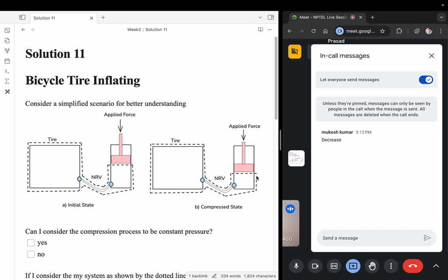in the question directly, but then you have to come to these conclusions. Either the question will tell you that it is insulated, which is a very straightforward one. If it is insulated, then it means there is no heat interaction with the surroundings. And then come scenarios like this, where the process happens so fast that even though your Q in terms of watts might be too high, the amount of time that the process is taking is so low that the energy interaction, Q times delta T, will actually be very low. So net heat interaction will be considered zero, and even in those scenarios, even though the piston is not actually insulated, you can consider that to be an adiabatic process.